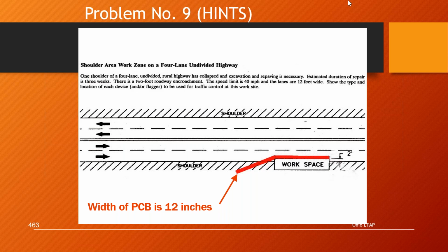And anytime we're dealing with high-speed traffic or high volume or restricted sight distance, we want to include the options that are shown in each typical application, whether it be more signs or more high-intensity lights, or the arrow board, or truck-mounted attenuators. Those are all options. Sometimes police can be used in your advanced warning area or in an intersection. We learned how to flag properly. Talked about mobile operations, and I went over some things on street closures and detours.